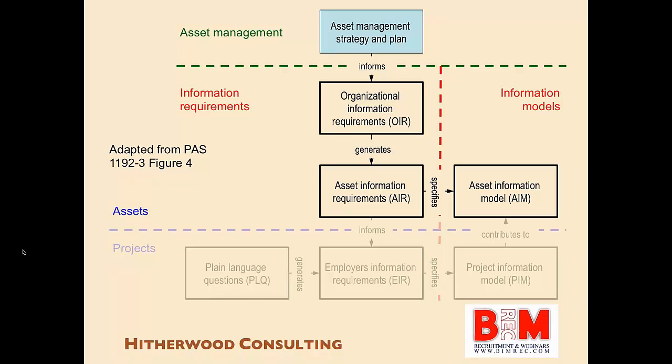And those information requirements are setting out what is needed to be delivered by the asset management contractors, the various people working on the asset as part of their contracted tasks. The information that they provide back to the asset owner or operator ends up in this thing that we're calling the asset information model. And that is the repository of information from which the organization can analyze and assess the performance of its assets to make sure that they are supporting its business activities in the way that it expects.